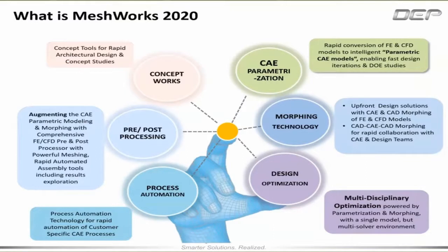And we use a lot of generative design and topology kind of optimization techniques to configure our structural layout, which is mass efficient. So even at that point, these topology studies and generative design inputs can all become inputs, and we can generate a workable, manufacturable concept out of that using MeshWorks. So that's a very important ingredient that we are going to showcase today and how it really helps. And regular pre and post processing is also a very good addition.